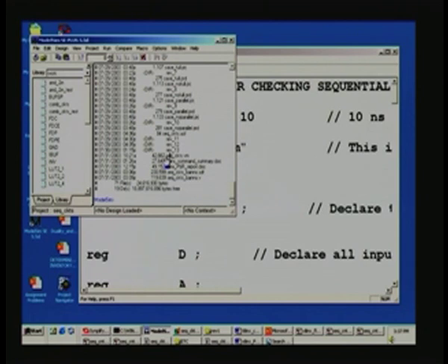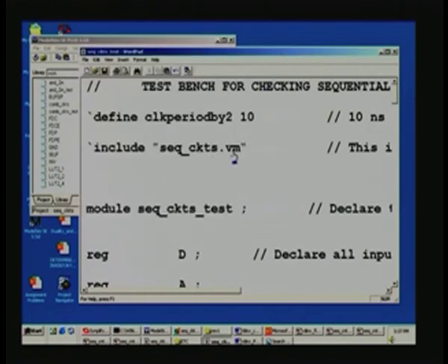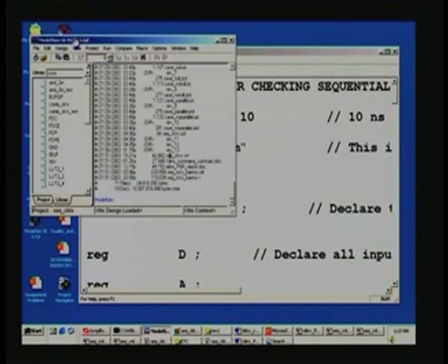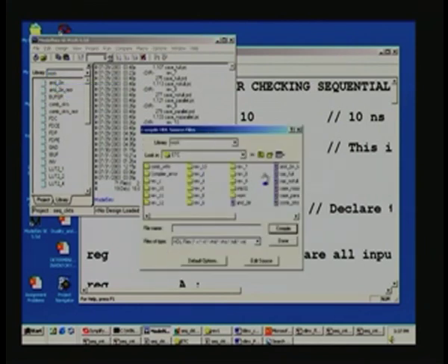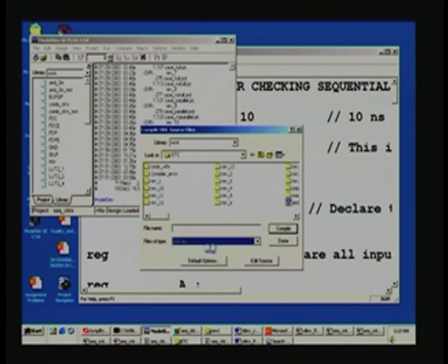and so now what we need to do is compile this once again. In this test bench we have replaced it with the .vm file, so it will take this as a design file now and then compile. So, let us see what it says. Now go to compile, design, compile window opens, and here we need all files at the bottom, then only you can view this.